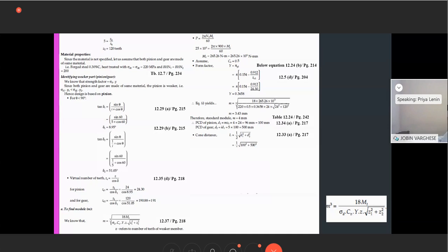Okay. And there is a question: if it is given to take steel as a material, can we take any steel, like cast steel, stainless steel, etc.? Yeah, sure, you can take that. It doesn't matter. But the concept of the design, at the final stage, is that we always make the gear stress less than the permissible stress. That is a major factor here. So we will be checking the sigma d continuously, even after every design step.